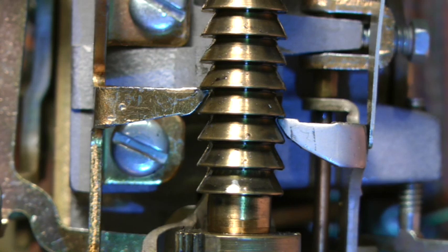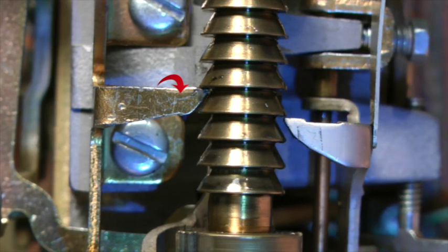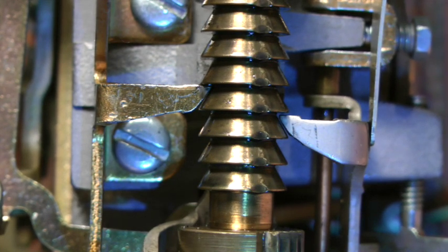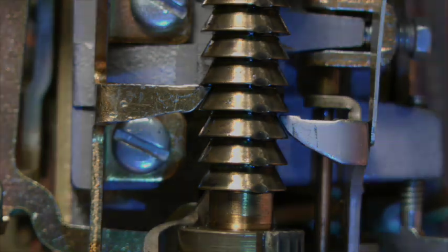When the shaft begins to rotate clockwise, the vertical ratchet channel rotates away from the stationary dog leg, which now engages the underside of one of the ratchet's teeth. This leg provides support for the shaft during the clockwise rotary stepping. When rotary stepping is finished, the stationary dog leg holds the shaft fixed in its vertical off normal position for the duration of the call.